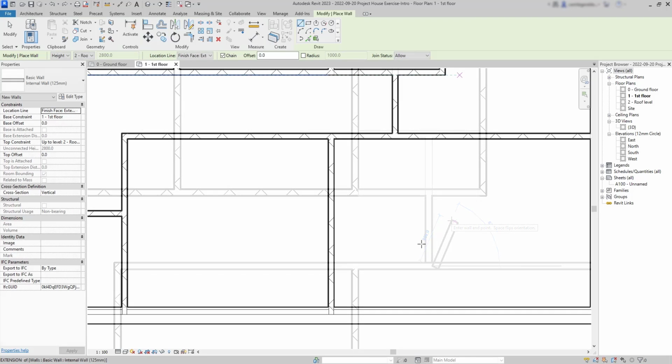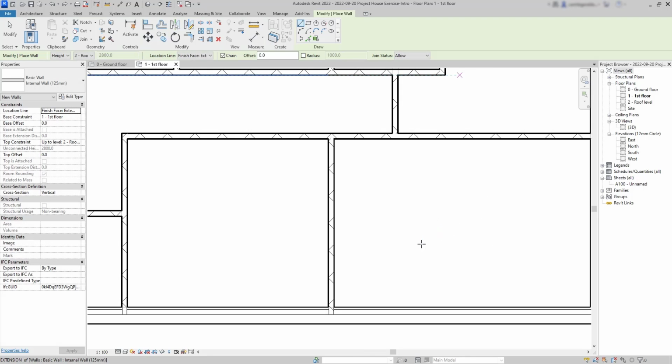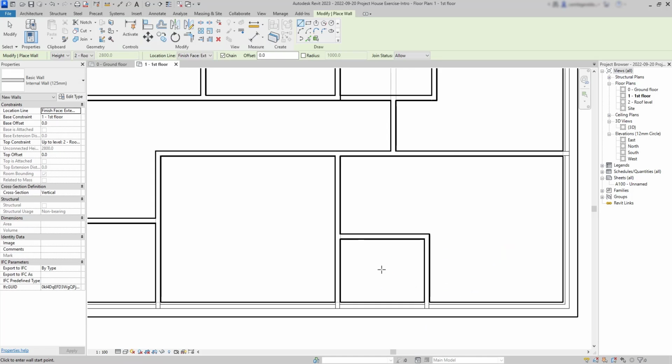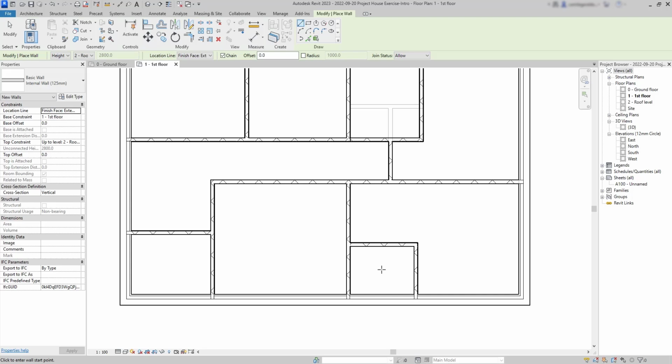And now look at this tip. Actually, to draw a wall in an exact location, it's not required to have the endpoint. As most of the time, if you place the pointer at the wall, this temporary length appears, and we just need to tag the value. Then, this time, as this distance will be 2 meters, look that it's also easy to place the right length by only moving the pointer. So, we have finished all the walls in this exercise.